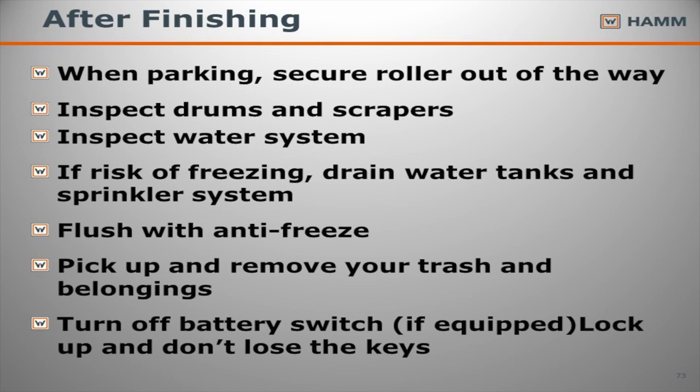Inspect the drum and scrapers. If you're going to be traveling, make sure you have them in the up position so they're not wearing out. Inspect the water system, clean the filters if you have a chance, because I've seen some of the water everybody uses. Some of it's not the cleanest stuff. If it's got a risk of freezing, we can either drain the water tanks or we can put in antifreeze through the system. Pick up and move your trash off belongings.